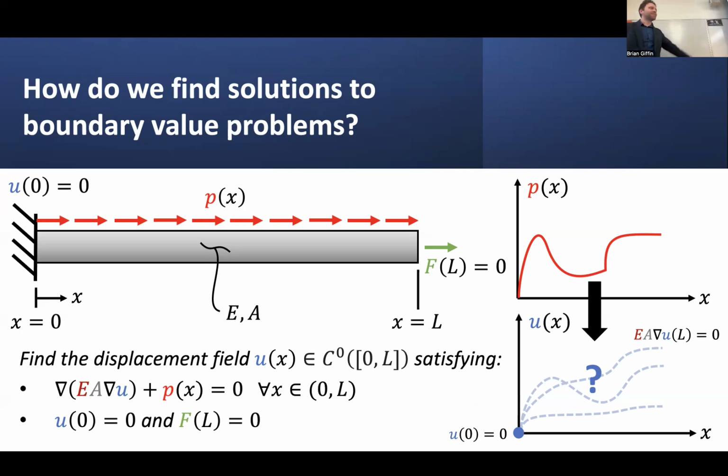let's say, one-dimensional structure, subjected to some externally applied loads, maybe a distributed load applied over the length, maybe an end load applied at one of these external boundaries of this domain, and also subject to additional boundary conditions on maybe the displacement field itself corresponding to any constrained supports. So in that setting, it becomes a direct constraint on what the value of the displacement field is at this particular location, let's say x equals 0.